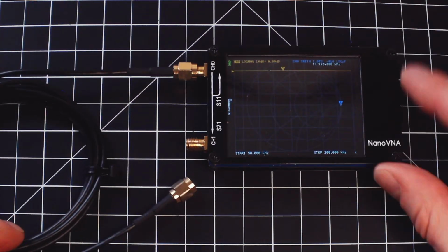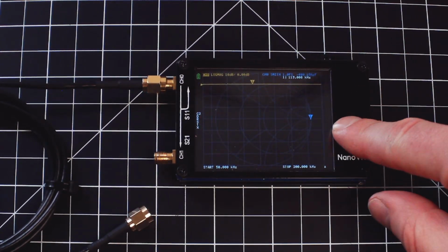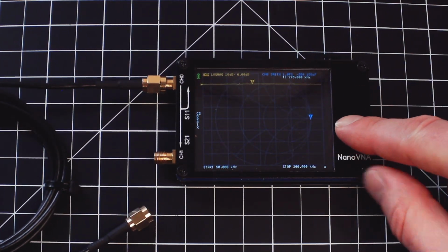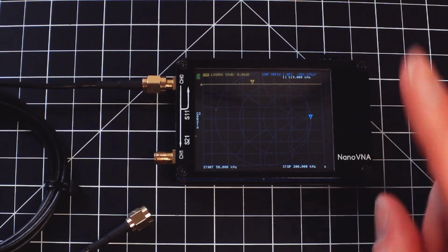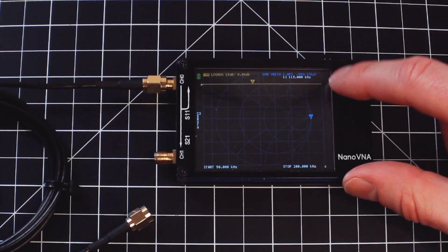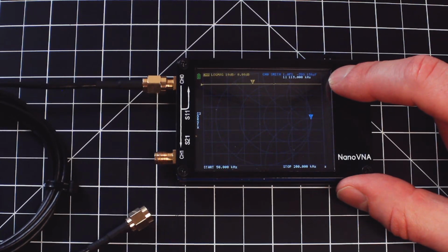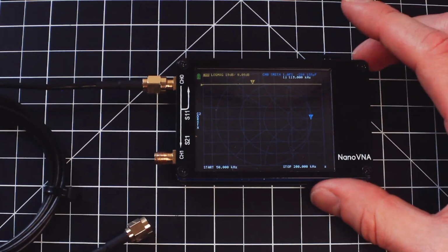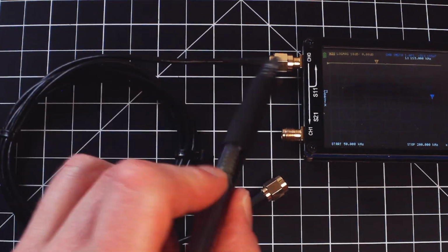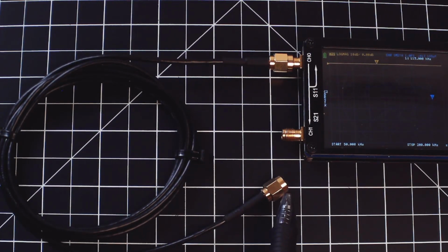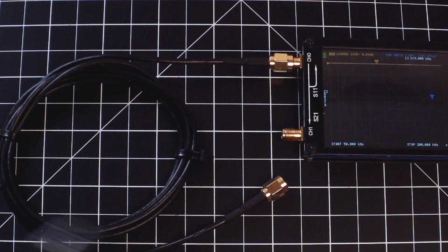And you can see that the NanoVNA, all it sees is an open circuit. Barely anything has changed. But it's been tweaked just a tiny bit, and it will actually return what it thinks is the equivalent capacitance of this load. So what's happening is it's sending out a signal which bounces off the open circuit here and comes back.